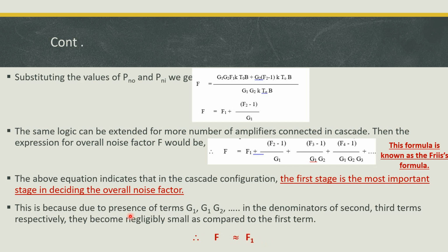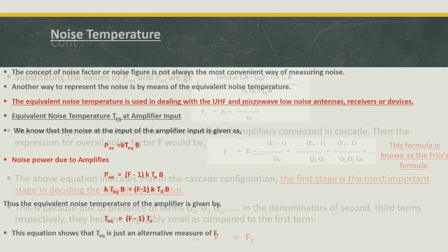So then we have to apply the input signal carefully by calculating the signal to noise ratio at the input side. You have to maintain the maximum signal to noise ratio, then only the noise factor will be less.